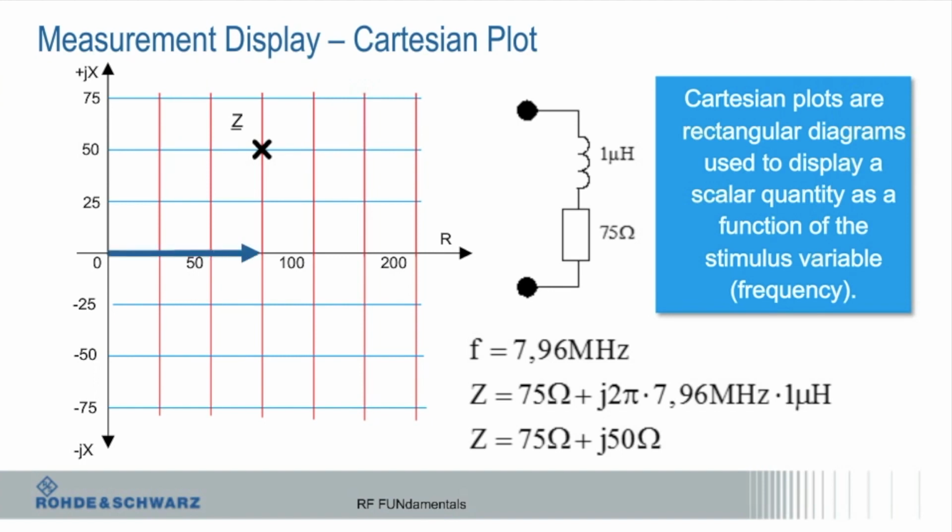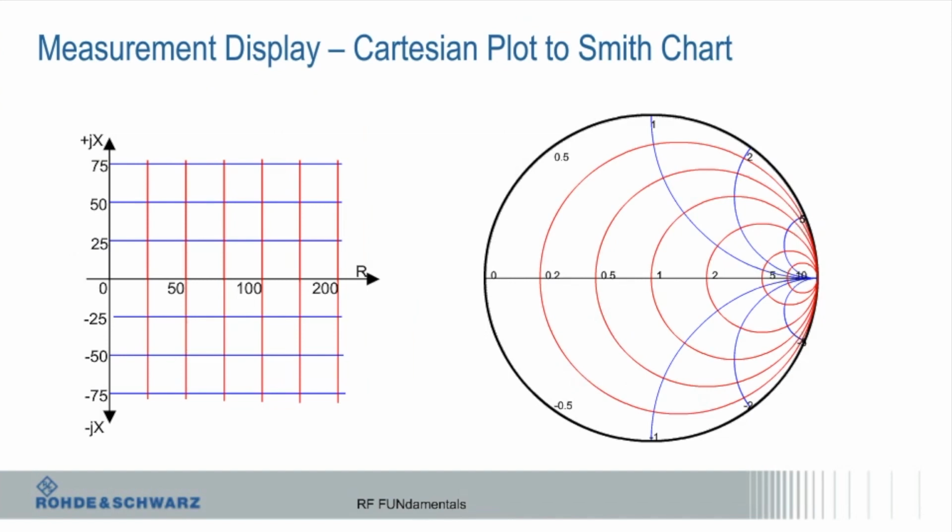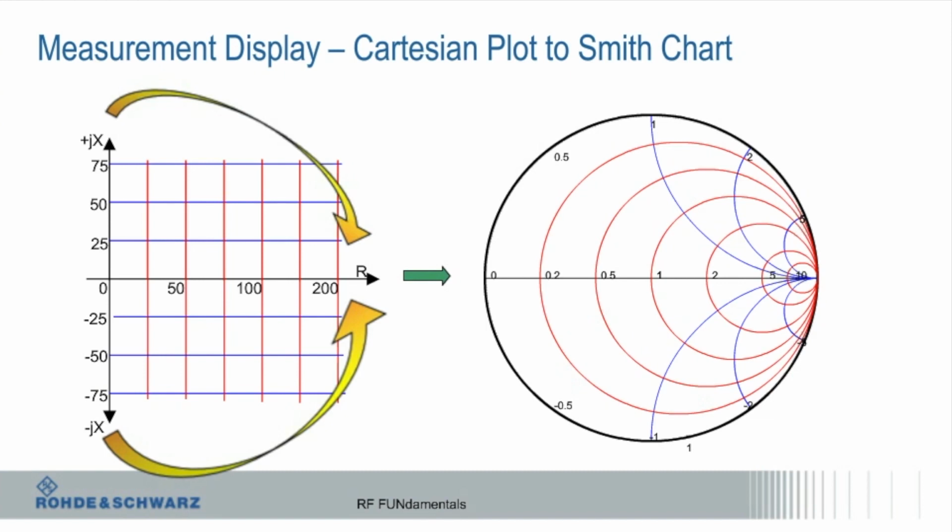Cartesian plot, so you see this is real versus complex impedance. So it's showing you a point on there. This is a common one for more gray-haired microwave engineers. Not to say it's not important to everybody, but the reality now is more of the components that you buy are already 50 ohms, so you're not going to have to match them. What historically people would do with a Smith chart is you'd take an amplifier, for example, and it would give you some points on a Smith chart, and you'd want to get those to 50 ohms to match to whatever your load is or your input is. And so you can use the Smith chart to get from one impedance to another. And it'll tell you what length of line do I need, what complex impedance, what real impedance.